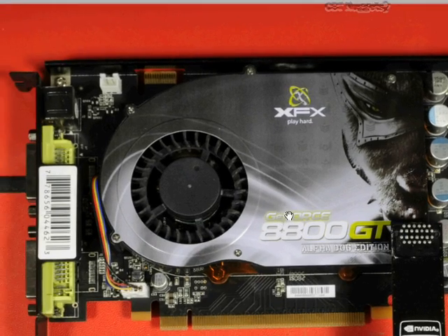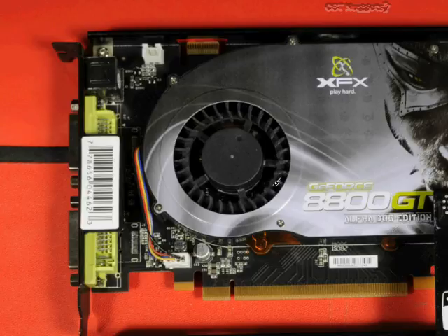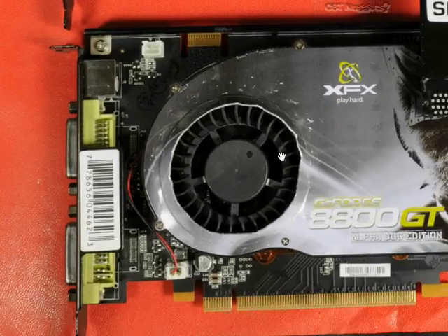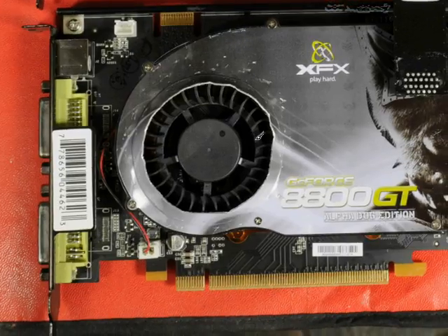I just want to share this real quick. And this might be useful in your own troubleshooting as well, by the way. But I had ganged these two together in an SLI connection, and I didn't seem to be getting the video performance that I expected to get out of these connection combinations. And I looked at this video card, and it was working just fine. The fan was spinning just fine and everything. And I had the cover off the computer so that I could observe this. And then I looked at this video card, and this fan here was seized up. It was not moving at all.